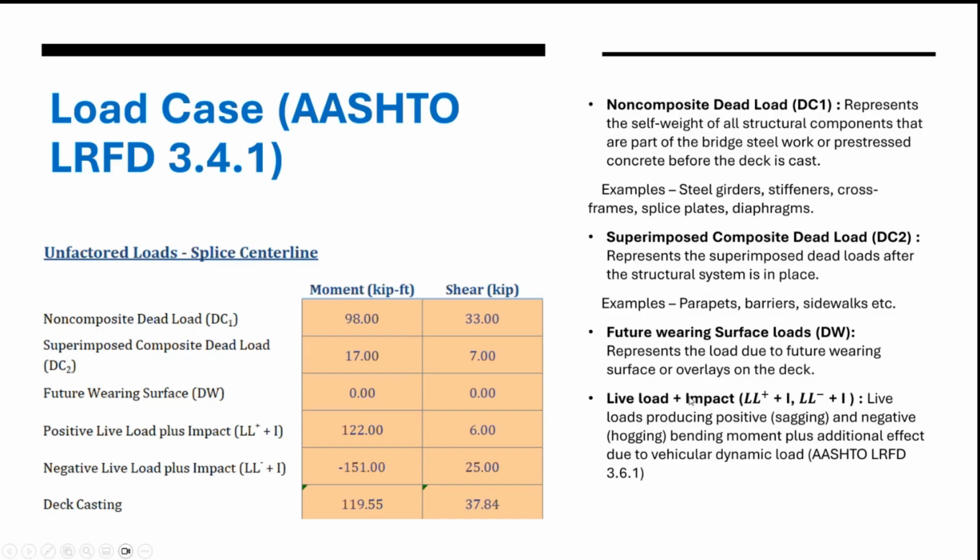And we also have the live load, producing positive and negative bending moment, plus the additional effect due to the vehicle dynamic load impact, which is also taken into consideration for the calculation of the splice design.